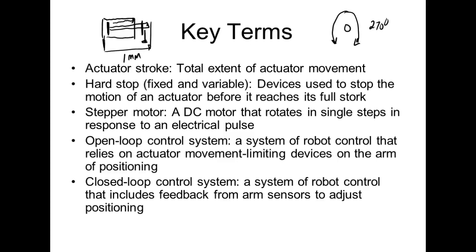But stepper motor. A stepper motor is a special DC motor that rotates in steps. I'll probably have to get that next class before I can show y'all one of these. I can show you a big one that's taken apart. But what we do is we send pulses to this thing, and for every pulse it rotates a precise number of degrees. This is probably one of the most popular motors used in open loop systems.